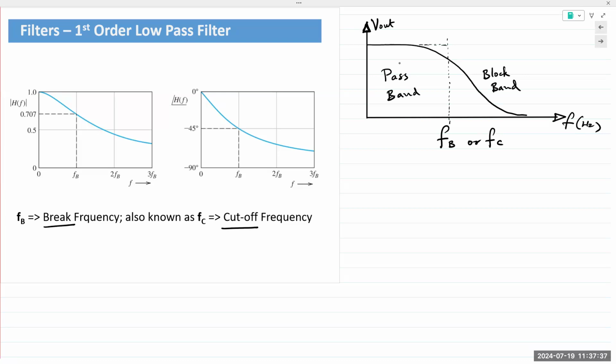In real life, there is no sharp drop. Okay, filter design is a specialization within EE itself. Okay, it's an entire specialization. So filter design, you can have first order, second order, third order, higher order filters. There are trade-offs that can try to approximate the sharp drop off. Okay, but in real life, there's never a sharp drop off. That is always a curve.